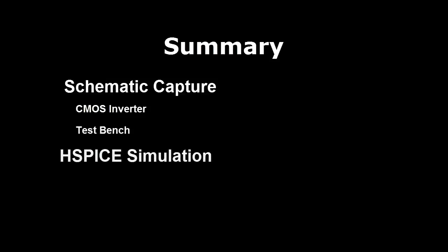We have shown you how to design your CMOS inverter using the schematic capture, how to design the test bench using the same tool, and using HSpice assisted by the SAE tool in order to simulate your test bench.